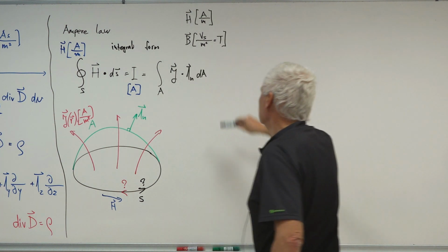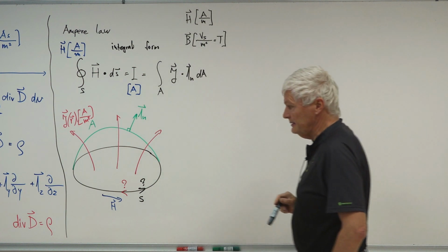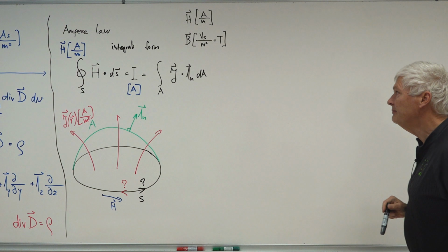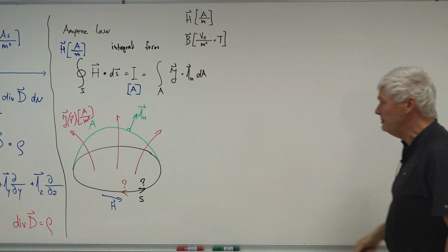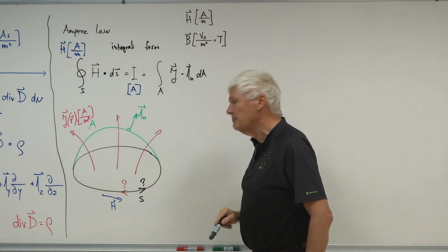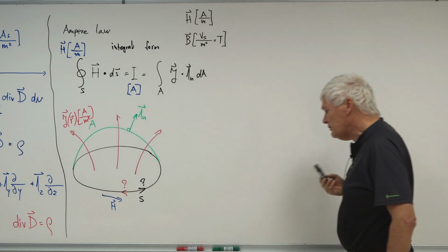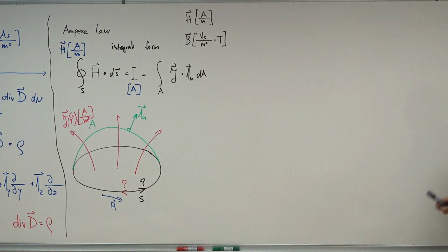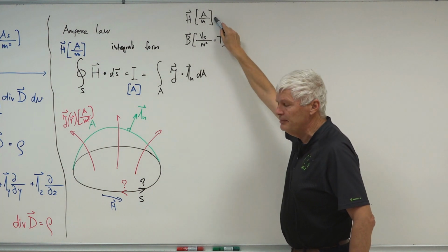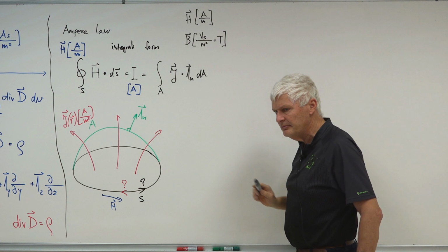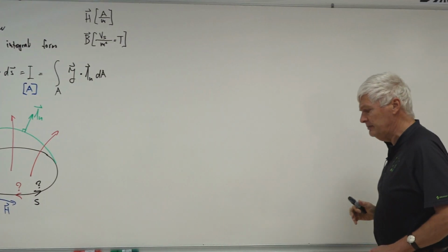Maybe it would be better to call this magnetic field intensity and this thing here magnetic flux density, to separate between the two, but this is a problem with the units. So we have three problems: finite dimensions, direction with the right-handed screw, and in English literature two different quantities that bear the same name. Usually physicists prefer the vector B, electrical engineers prefer the vector H. This is the way it's usually done, but they call them both magnetic field.